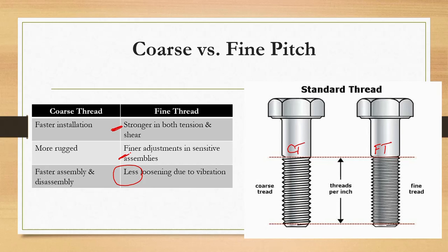They cannot be used in very rough environments because of the small size of the threads. Because the number of threads is large, the thread size is small, so it could quickly fail and result in failure. So they are generally used in a very safe, low temperature, low humidity environment, where temperatures or humidities are not very high. So again, everyone has its own application.